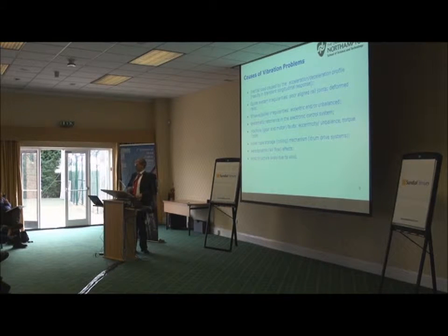As we will later show, there are systems which have a number of pulleys, and always there is traction sheave. When you have an eccentric or unbalanced defect in the system, it will cause vibration. We can have a systematic resonance in the control electronic system, and we know, for example, that the issue of torque ripple is the issue. We have other faults in the machine, gear systems.